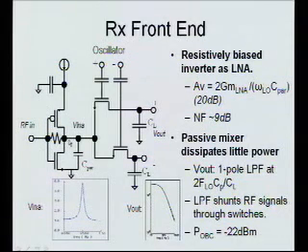And by output linearity, which is if I swing this too much, I drive these into triode. What I've just done here is suppressed my out-of-band signals by about 10 dB. And so I've made my output nonlinearity for out-of-band signals 10 dB better. What it ends up doing is it means I can have a hell of a lot of gain and still have my linearity smashed out of band, so that I compress the input and the output about the same time. So that's a really fun little trick out of an insanely simple circuit.